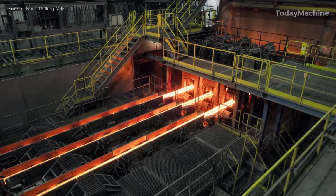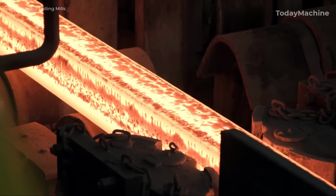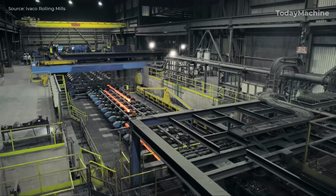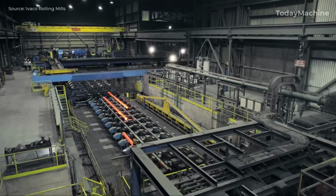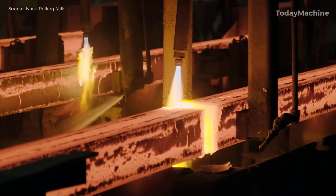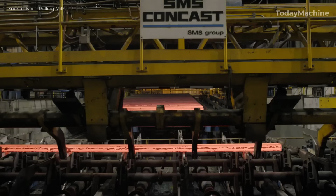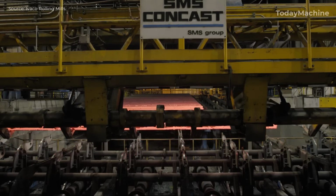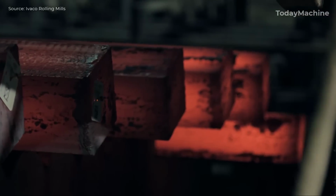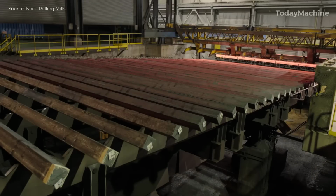The next stage is continuous casting, where the molten steel is poured from the ladle into a tundish, a reservoir that feeds the steel into the billet caster. The caster draws the steel downward through a series of support rolls while water sprays cool and solidify the metal. This process forms the steel into billets, long rectangular shapes that serve as the starting material for rolling into wire rods.